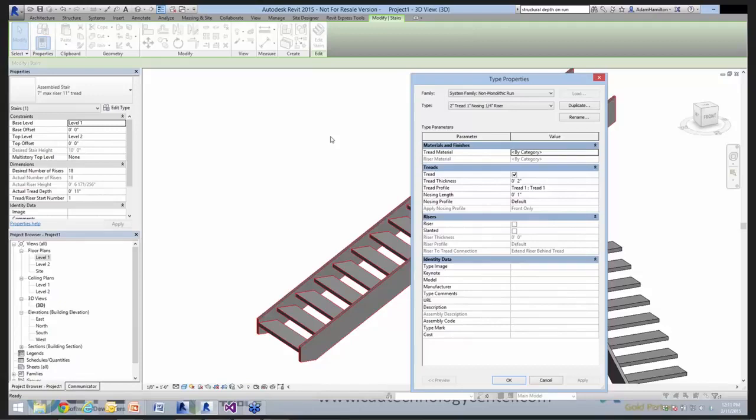And so any sort of modifications to those pieces can't be done utilizing the stair tool. Sometimes they're utilized with in-place families or wall elements with modified profiles. In that case I was just talking about, it could be a riser family with perforations, and so being able to turn it on or turn it off gives us the ability to manipulate those things as well.